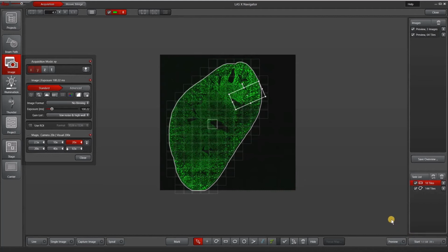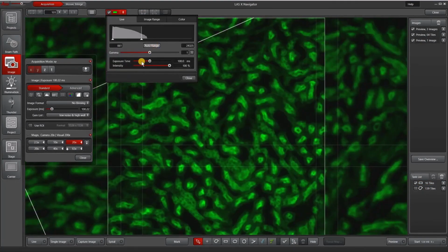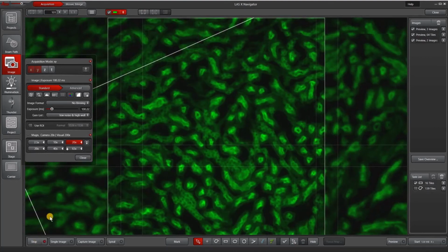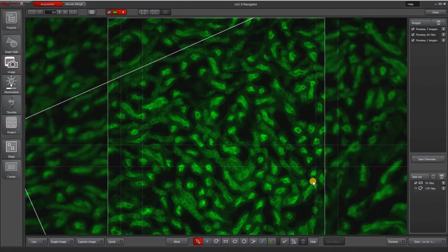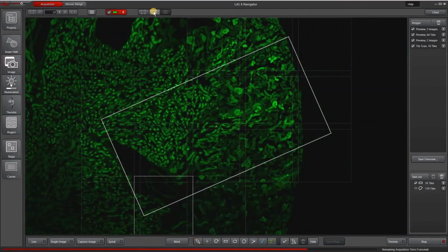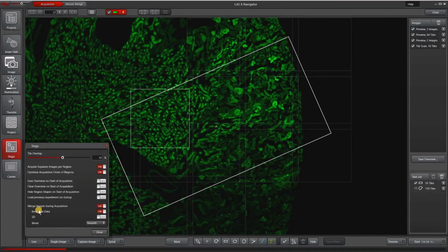When I switch objectives, I of course need to adjust my imaging parameters and focus. So let's go ahead and maybe do the smaller region here. Let's double click to this area. Zoom in, and let's go live. So after I've adjusted my focus and my exposure and I'm happy with my image, I can go ahead and click start. I have finished my scan, and because I have clicked merge images during acquisition, it merges it immediately after I've acquired the images, and I've also asked it to keep the raw data.